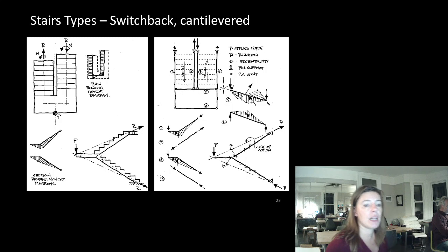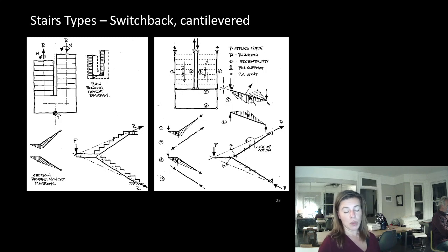There was a load case that I said, or if you look at it, it says 1 kilonewton causing less than 1 millimeter of deflection is a very handy load case. We also remember that 1 kilonewton, when in doubt, is a really good load case to use to test things out. Because, and we're going to see next week, that is specified in the code. A person doing something can't do more than 1 kilonewton's worth of damage, according to the code.